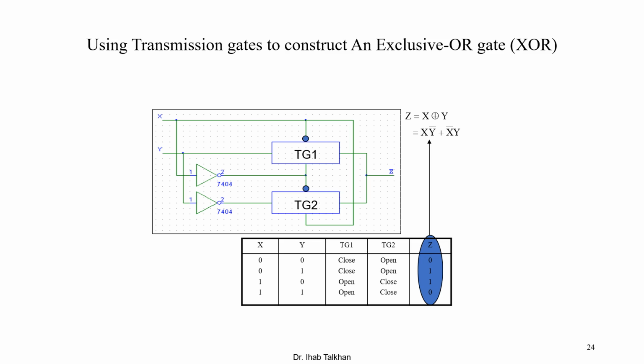In this slide, I'm going to give you an idea how to build an XOR. Before building it, you have to draw the truth table of XOR. The truth table of XOR is shown here. You have X and Y and output Z. You have Y as 0101, X as 0011, which means this is your input, and your output will be 0110.